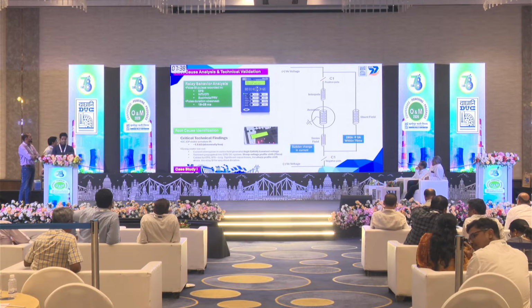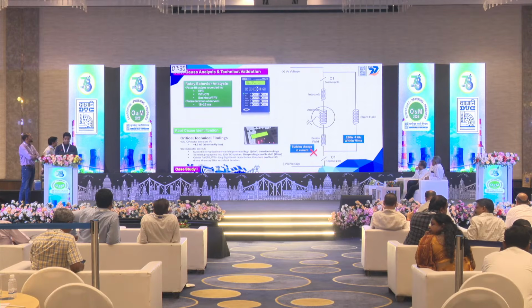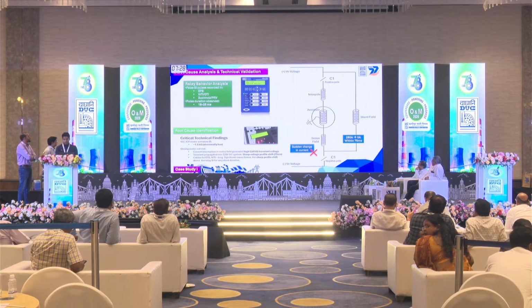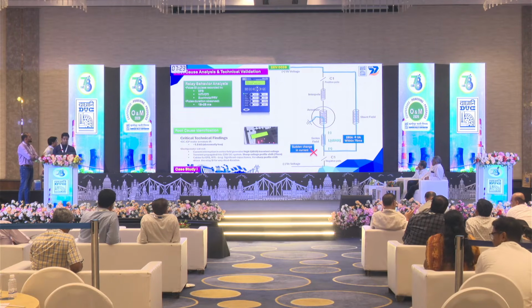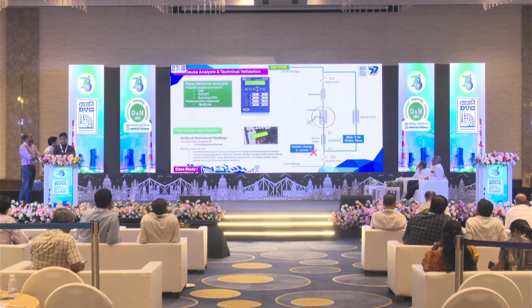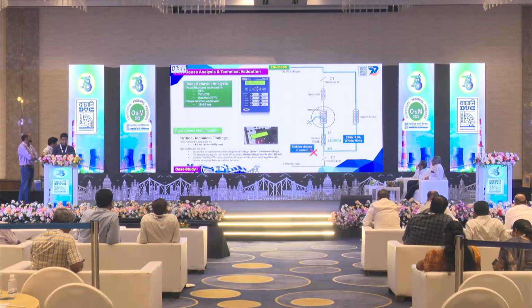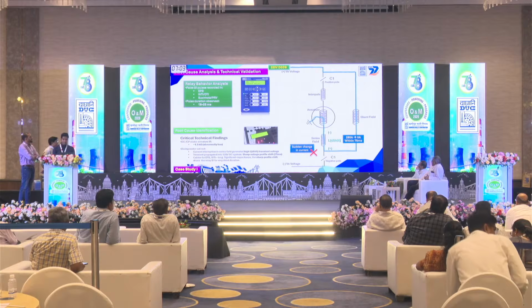Now let us see what was the actual reason for the tripping. We all know an inductor doesn't allow sudden change in current. But when we turn off this motor, because of opening of the C1 contactor, the current through the series field changes from 280 amps to 0 amps within 75 milliseconds. Due to that, a very high L di/dt transient voltage appears across the series field. Note that the armature is already grounded because of low IR value. So this high L di/dt transient voltage propagated to the 220 volt DC DB through the highlighted path.